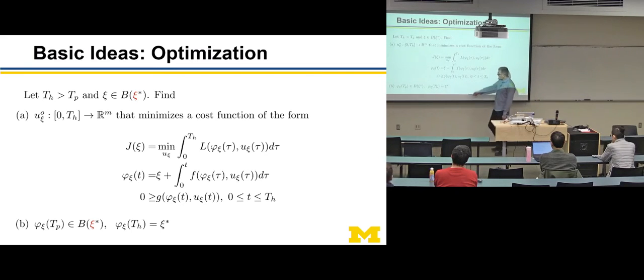And then we put a whole bunch of constraints, and the constraints are my torques can only be so big. It's a robot. The motors have finite size and finite power, finite torques. The ground reaction forces that we talked about a little bit on Thursday, I need those to be in a friction cone. Some of my joints, I can't have my legs crossing. They'll bang into each other.